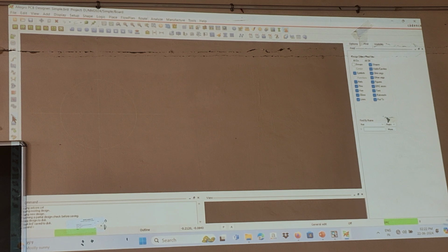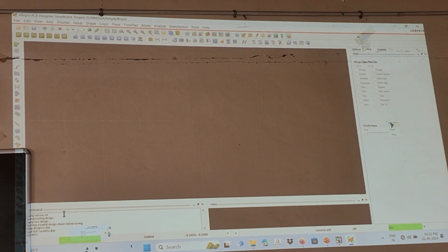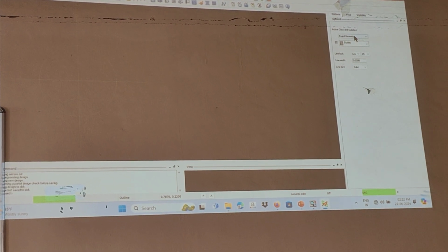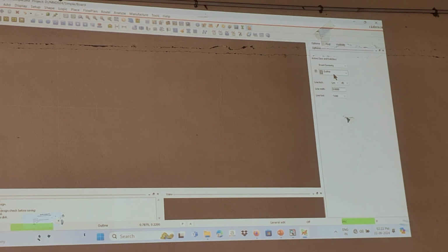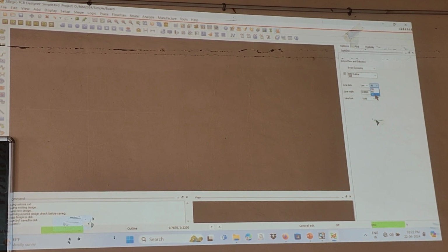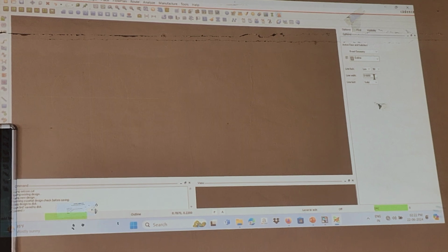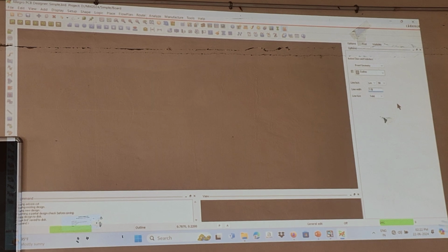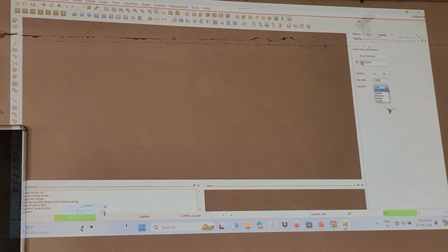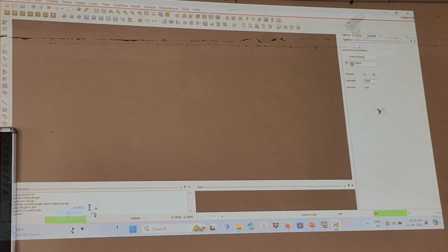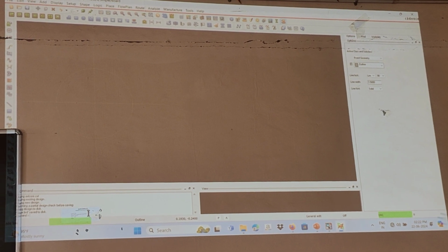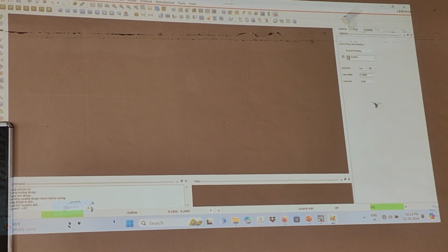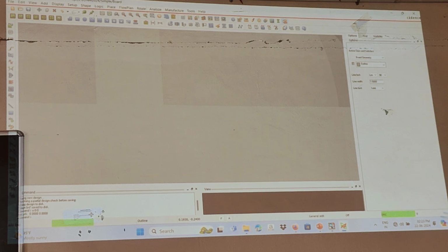And next I am going to place the boundary for the board. So I will just select add line and go to option and select the class and subclasses, board geometry, outline. The line lock angle as 90 degree. The line width of 1.5 mm, and line font also we can select, and go to command window and fetch the origin x space 0 space 0 and press enter.